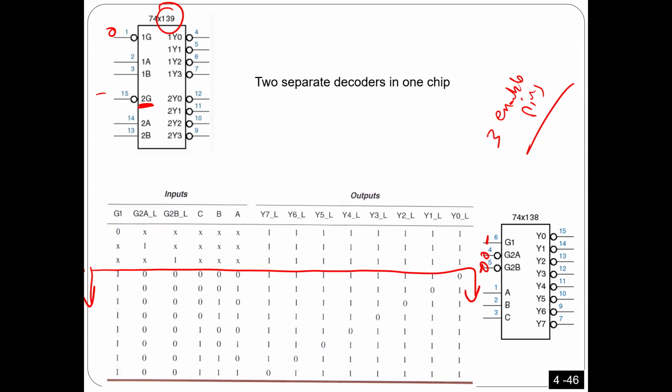all of this is the same. 100, sorry, enable. 100, you enable. Now if the input is 0, output number 0 is 0, and everyone else is 1. When it is number 1, output number 1 is 0, everything else is 1. When it is number 7, output number 7 is 0, everyone else is 1. Any questions? Easy, right?